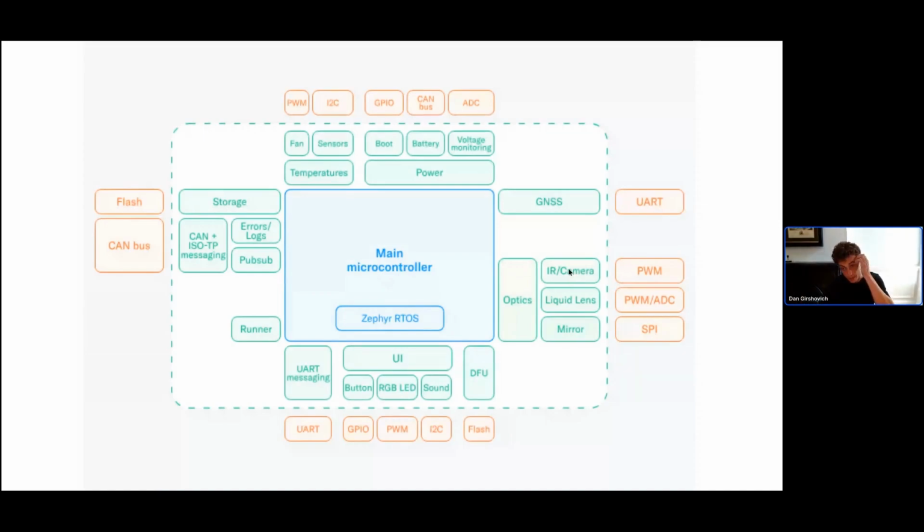And then critically, it can do real-time triggering. So we want to be able to control in software exactly when each camera is triggered. Maybe, for example, you want the illumination system to be running at 30 hertz, but then you want to trigger another camera just in the time between those flashes, to avoid interference. And that's done by using external triggers to tell each camera or each LED when it should flash or when it should do the capture.